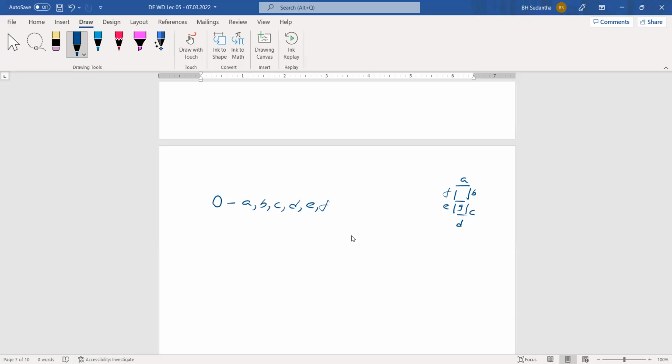We give logic 1 to these segments, and G should be 0. If you do like this, then we can turn on the relevant segments and the number 0 will be displayed.